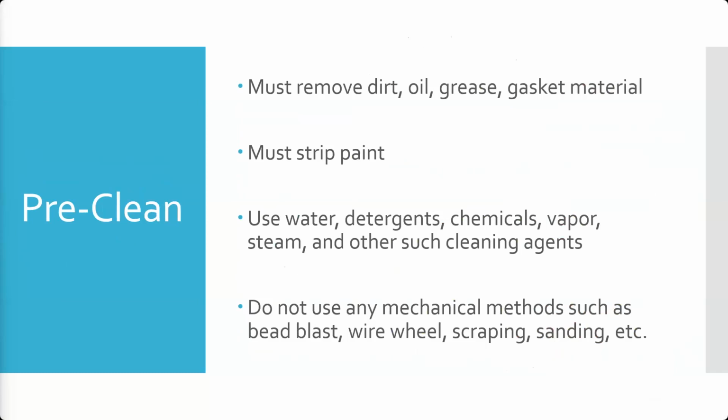Do not use mechanical methods though. If you use mechanical methods, you run the risk of basically peening any cracks or crevices closed again, which will prevent you from being able to get an indication. That includes things like bead blasting, wire wheel scraping, sanding, etc.